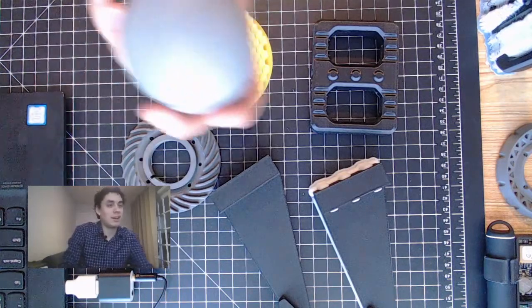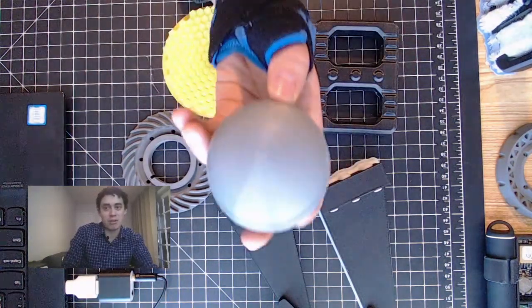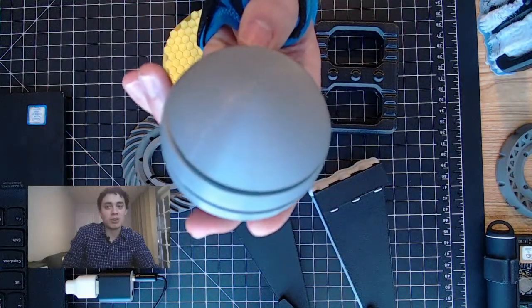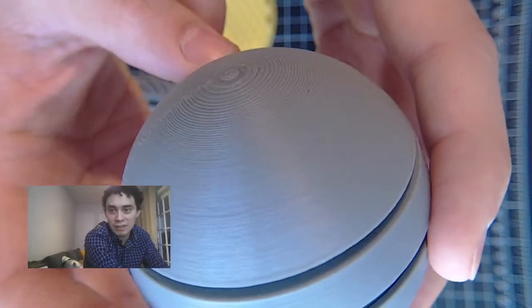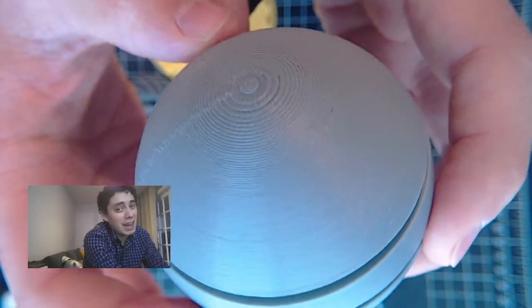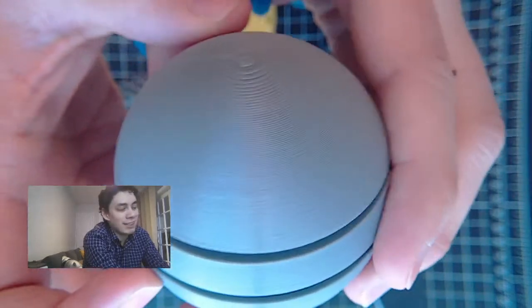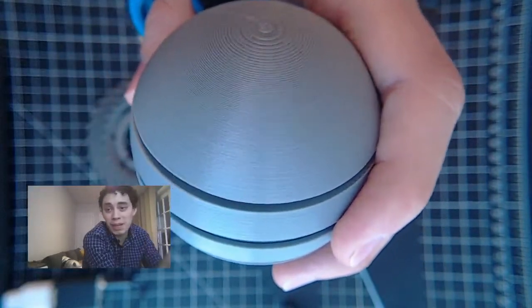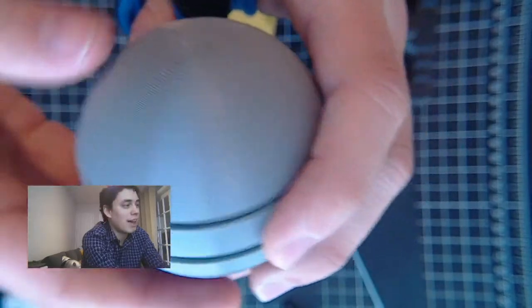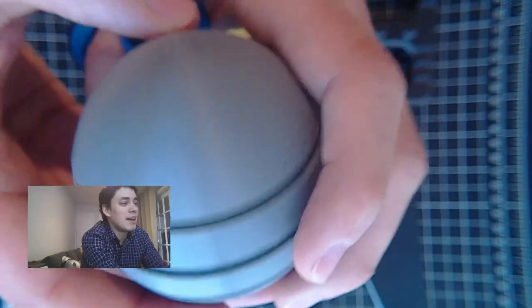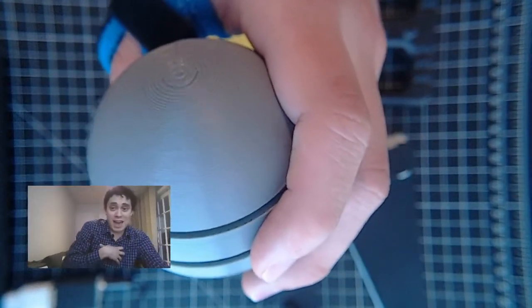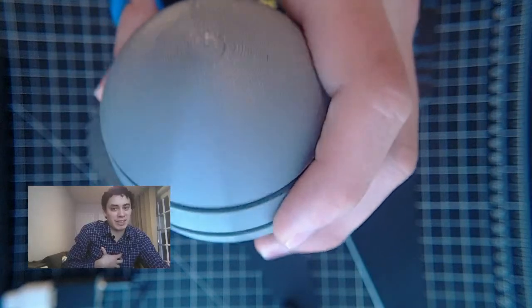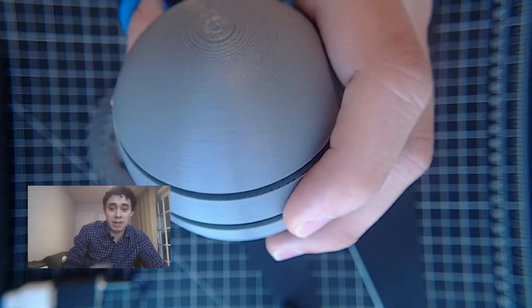part looks. I'll bring another example here to the camera, right? This particular sphere. Anything with curved surfaces will have a noticeable effect as the layer lines appear, right? If you want to get rid of the layer lines, I would strongly suggest either painting the part or post-processing the part, as opposed to trying something chemical. The layer lines are a byproduct of the 3D printing process. Personally, I like them more often than not. They tend to look really interesting to me in describing that shape.